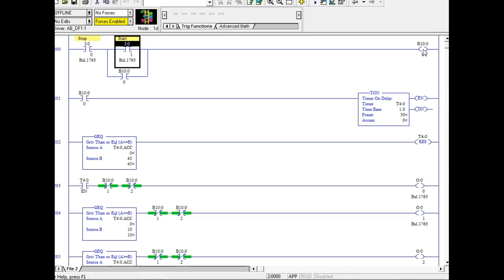in there. But if you upload it and you have the diagram still up, and you don't download it, right, you're going to have the symbols that you put in your program. Y'all understand what it is? So when you download to the PLC, symbols don't go. You close out of it, you need to work on that program, and you didn't save it or something happened or you lost it.